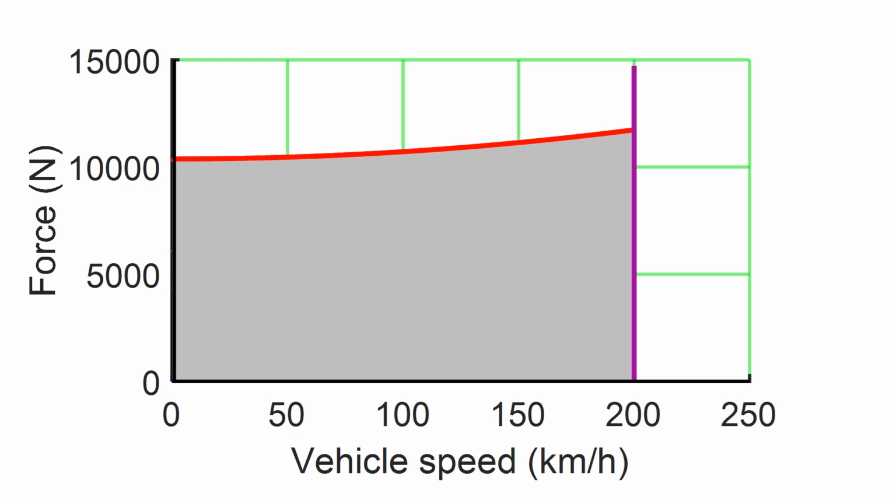Therefore, there is a good reason to reduce the force requirement if that does not make the vehicle less valuable. The first way to reduce the force requirement is to note that the steep uphill gradients are quite rare. Therefore, it may be reasonable to accept lower acceleration the short time the vehicle is driving uphill.